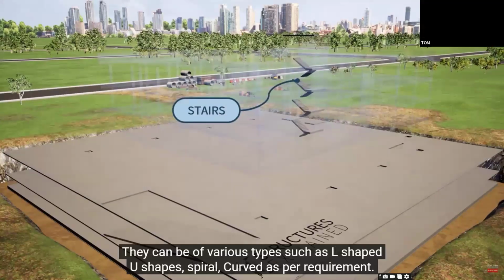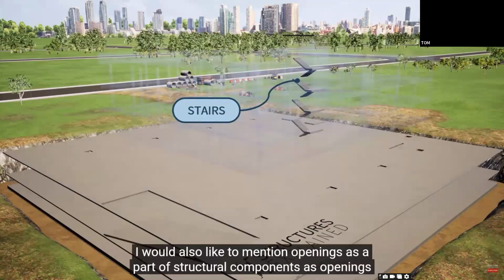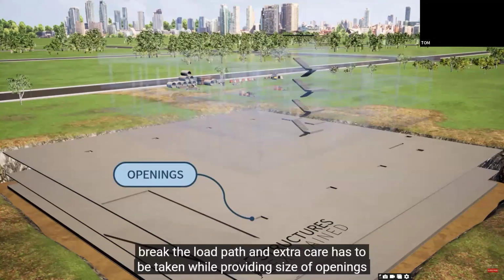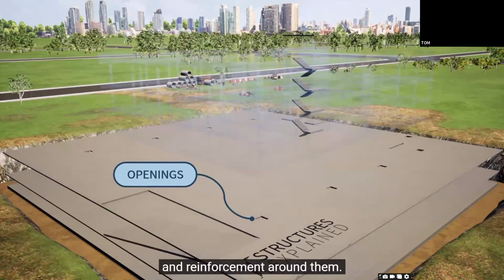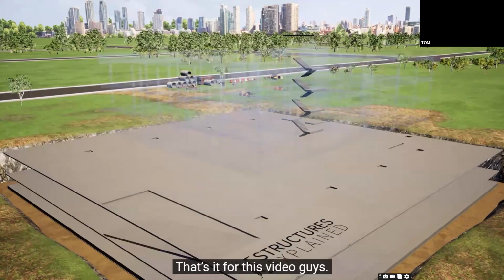Last but not the least comes stairs, which can be cast at site or come in pre-cast panels. They can be of various types such as L-shaped, U-shaped, spiral, curved, as per requirements. The stairs can be enclosed in a core wall like in this case or rest on columns and beams as per design. I would also like to mention openings as a part of structural components, as openings break the load path and extra care has to be taken while providing size of the openings and reinforcement around them. Openings are mainly governed by architectural or MEP requirements.